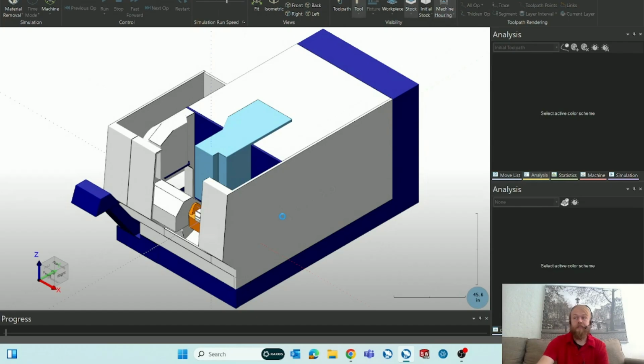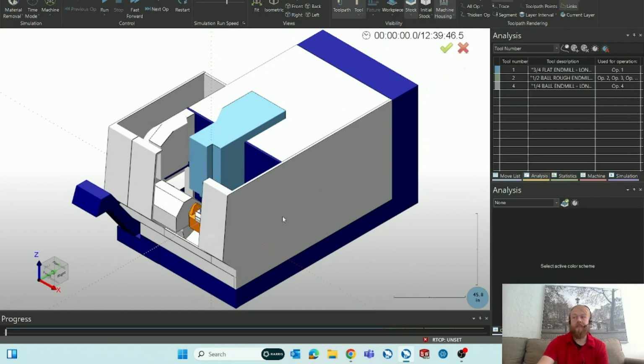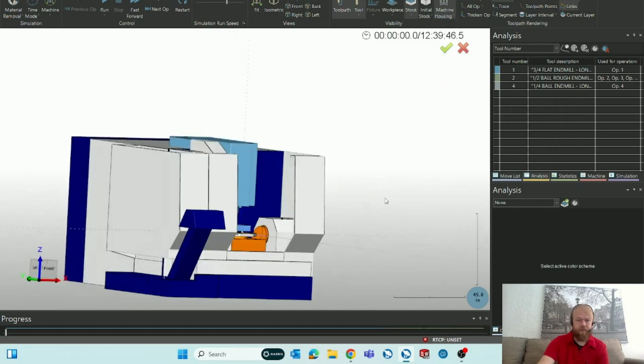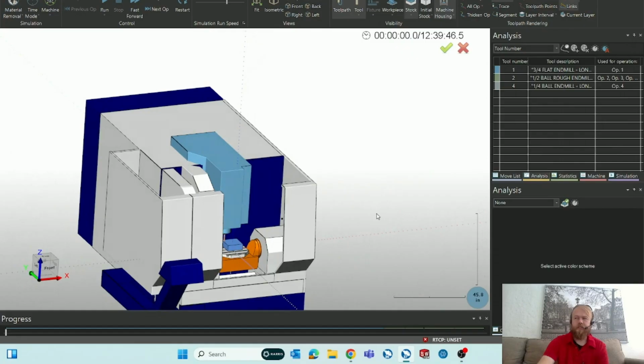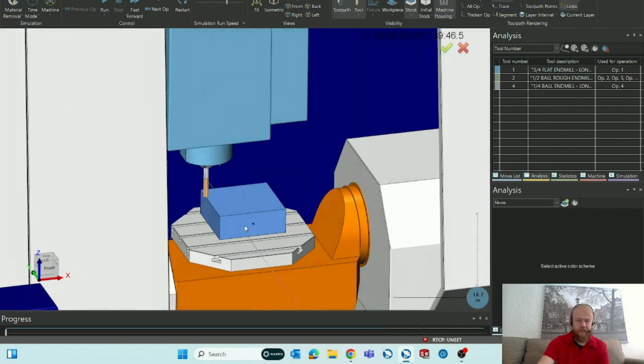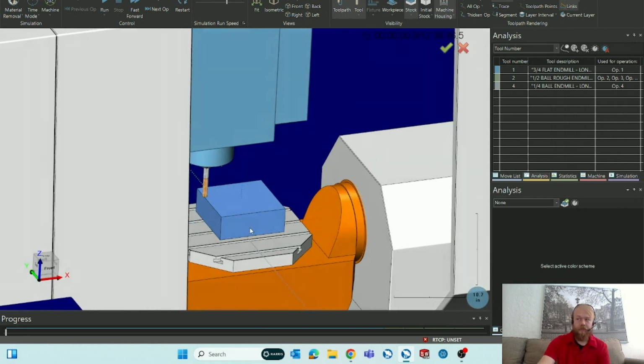Mark, good question. Is the advanced UI content the same as the Mill 4 or Mill 5 or Mill multi-axis settings? Yeah, so if you go into Mill 4-axis wizard or the Mill 5-axis multi-axis wizard, you will see those tabs just like you see in the advanced UI. Yep, they use the advanced UI settings as well. Mill multi-axis is going to be the same as the advanced UI there.